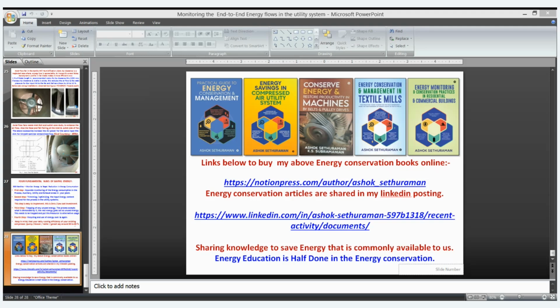Excellent. In fact, in many industries here we have done case studies on IE4 and IE5. We found one critical and one subtle input: wherever the loading is around 40%, IE4 and IE5 give excellent energy savings compared to IE2 or IE1 motors. The efficiency curve for IE4 and IE5 becomes broader, covering almost 25 to 30% up to almost 90% loading. That is a big area, because everything depends upon the production. If the given production wants the motor only at 40% loading, then IE5 or IE4 stands the best chance. Thank you, ma'am.